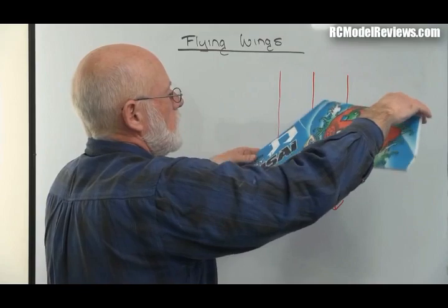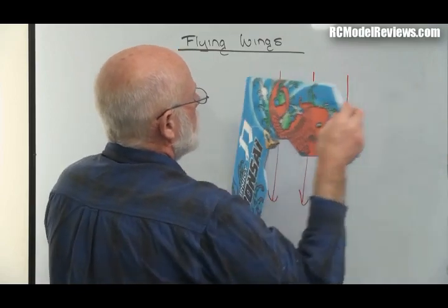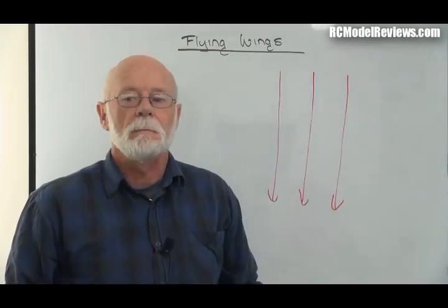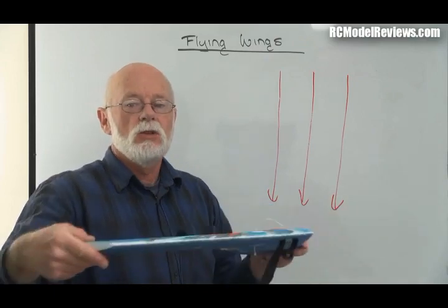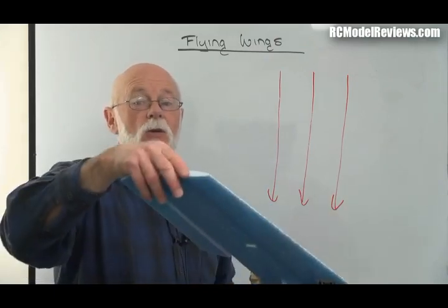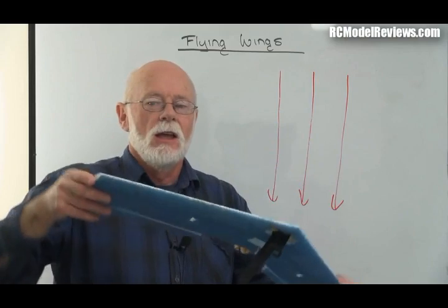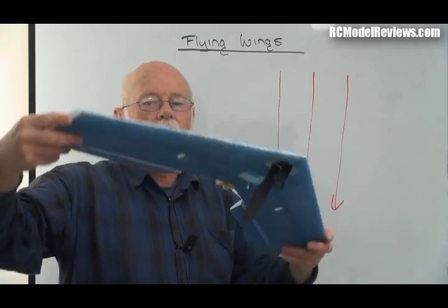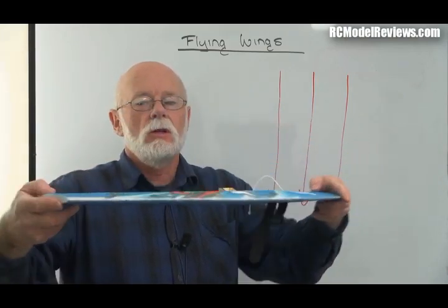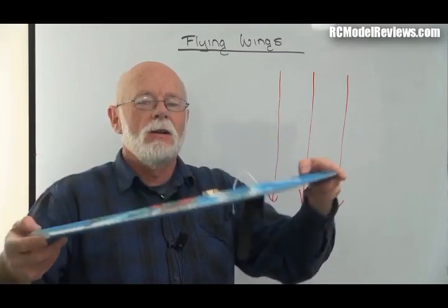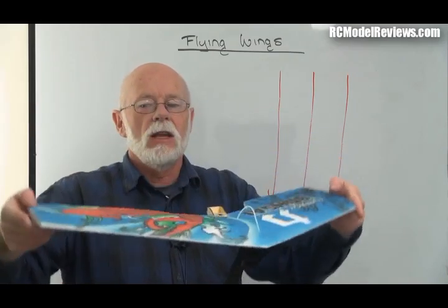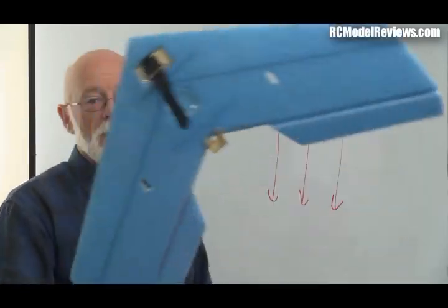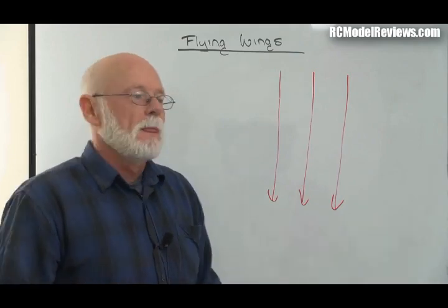So if you are flying along and you yaw this way, you'll roll that way. So there is roll-yaw coupling. The yaw produces a rolling motion, and it also produces a corrective yaw motion. So you can see this: you yaw, you roll, you yaw back, you yaw, you roll, you yaw back. And have we noticed on FPV videos that flying wings do this a lot? We do.